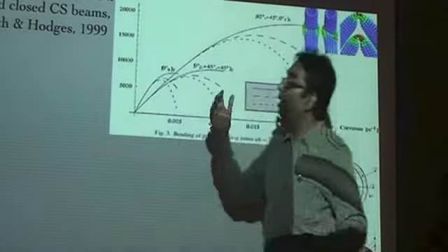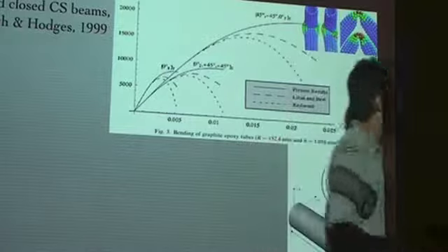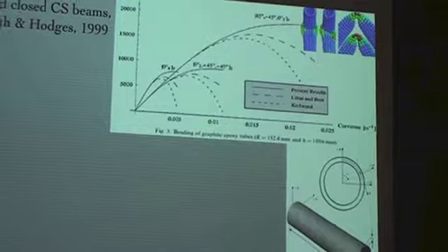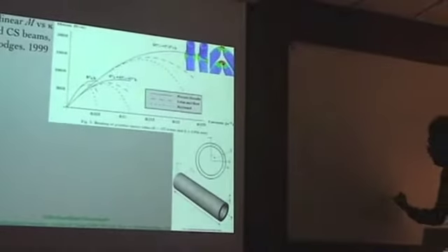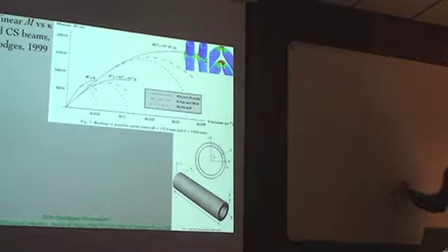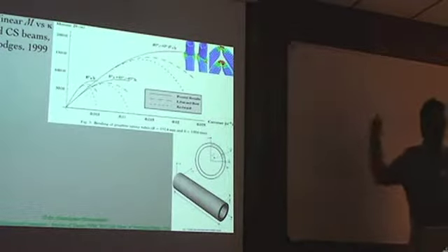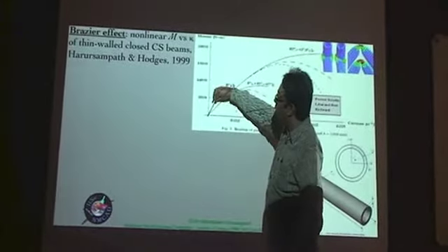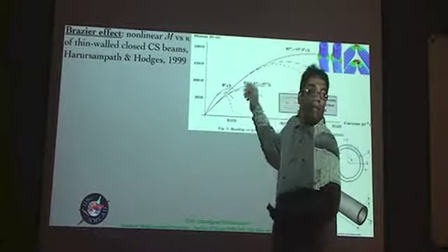And then you basically see that if you have a linear model, your bending moment is related to kappa 2 bar through this constant of proportionality EI2. So if EI2 is not changing, that is you don't take this nonlinearity into account, you should have a straight line with a slope equal to EI2. So that's basically what you would have as a slope over here or slope over here depending upon different materials.